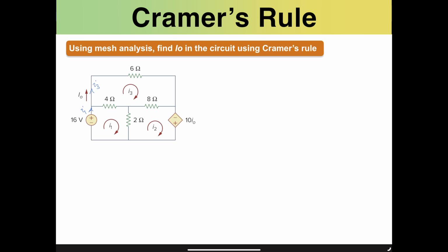I3. Then what is left in this analysis is I3 exits, I1 enters. So what is left is flowing to the right, but that is also simply I1 minus I3. So I would write I1 minus I3. So this is an inherent nodal analysis that we have employed here. So that is the current passing through this 4 ohms.